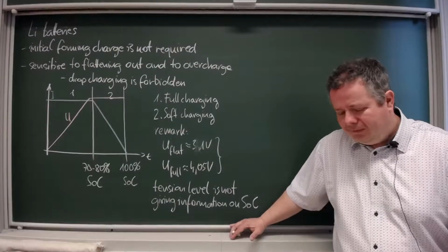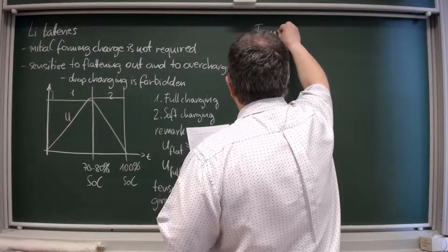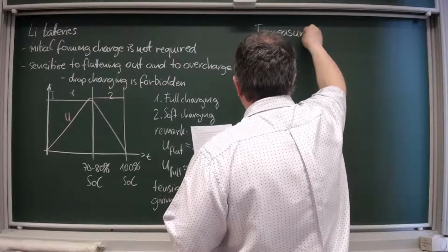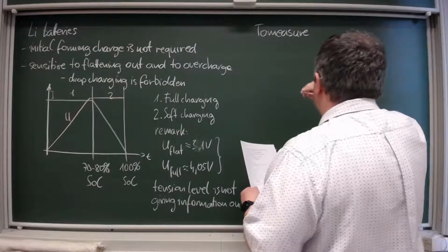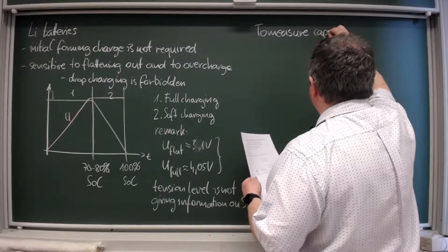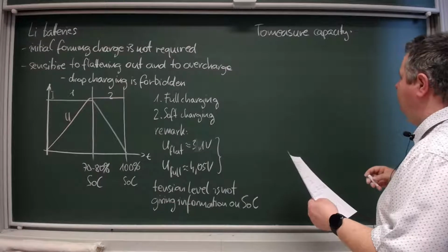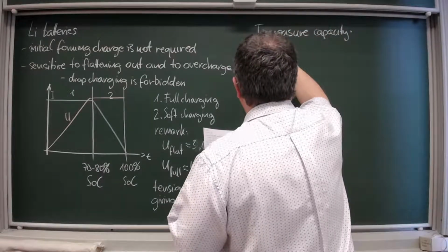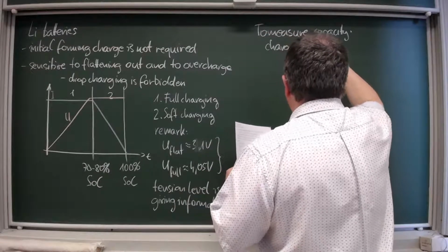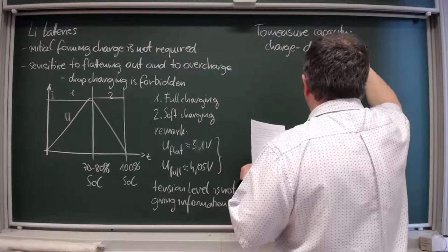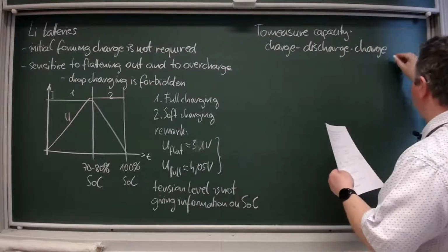What you do instead to measure capacity, you need a charge, discharge, charge cycle.